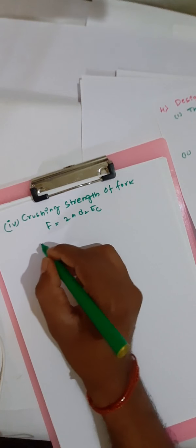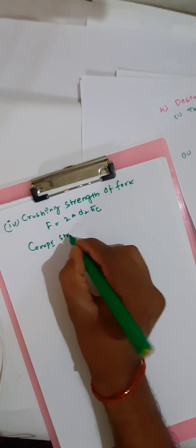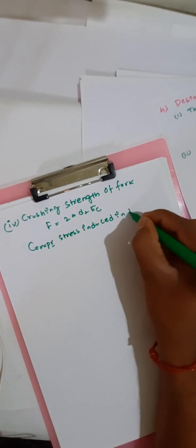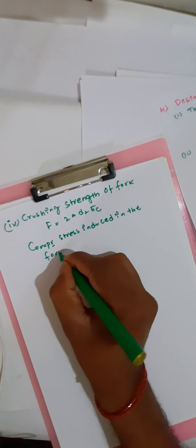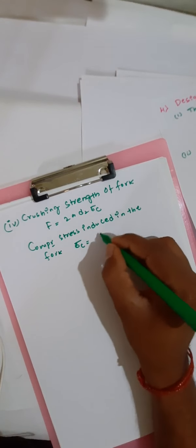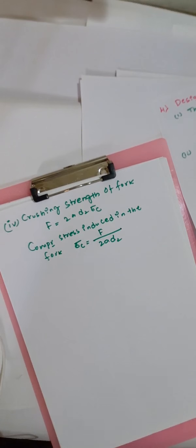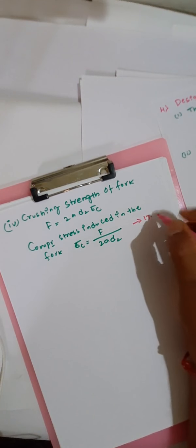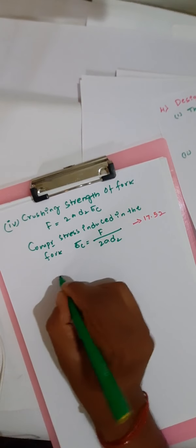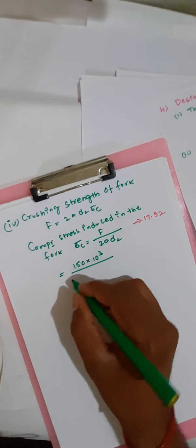The compressive stress induced in the fork is sigma c equal to F divided by 2a d2. This is available in the design data handbook, 17.52. If you substitute all the values, 150 into 10 to the power 3 divided by 2 into